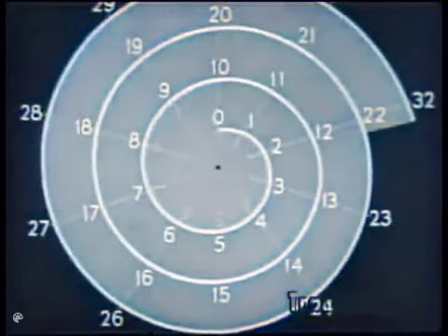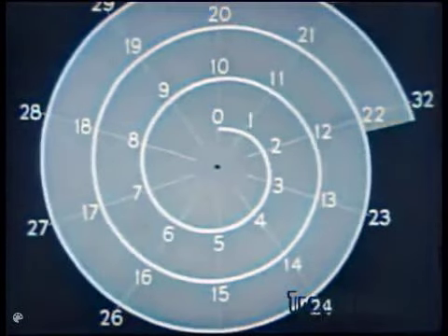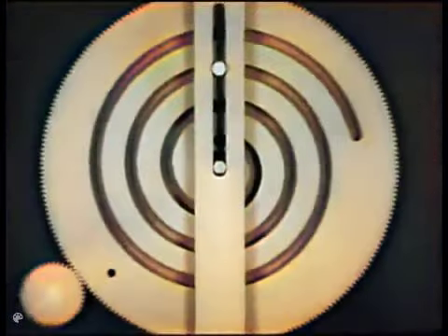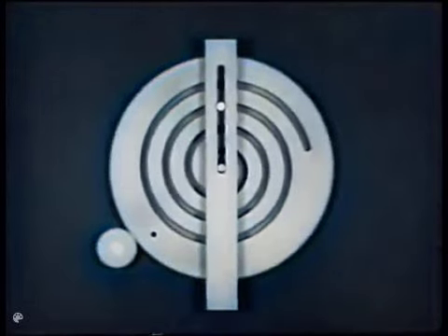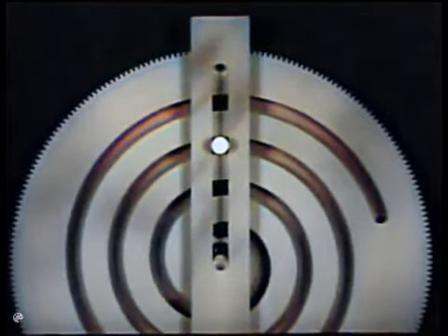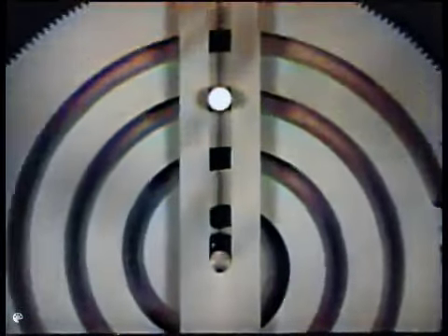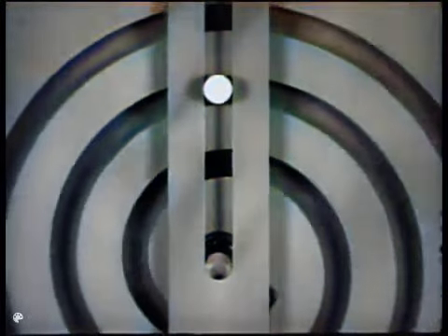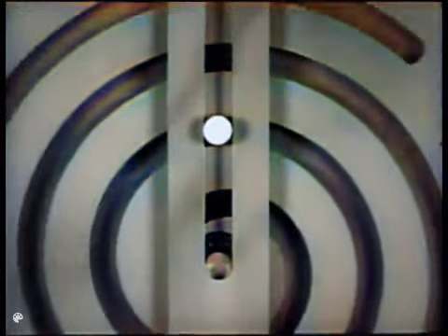Additional revolutions can be obtained by extending the working surface, which now must be a groove. An example is the constant lead cam, where the follower is a pin riding in the groove. In a fire control computer, a rotary input of ship's speed is delivered as linear movement of the follower.